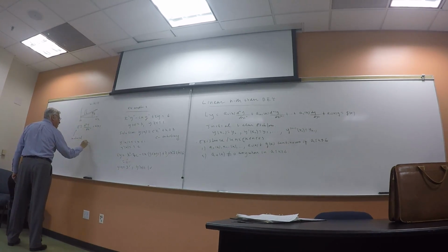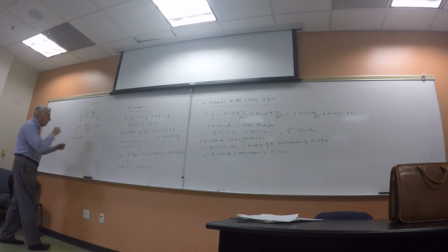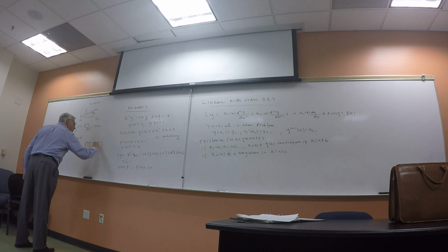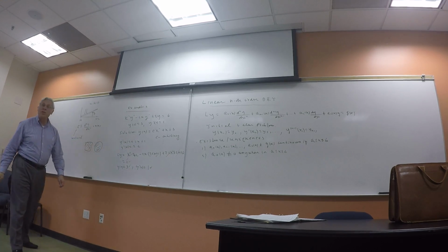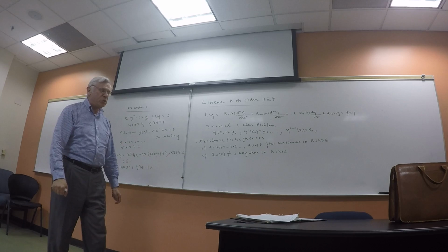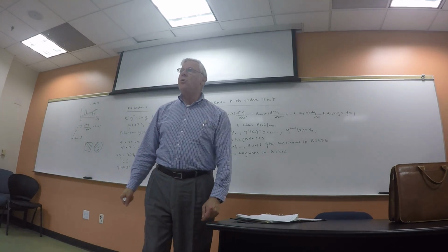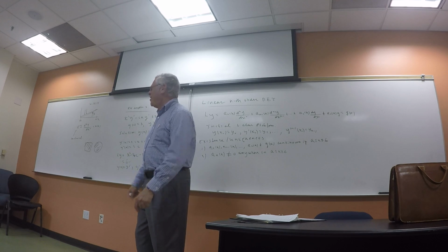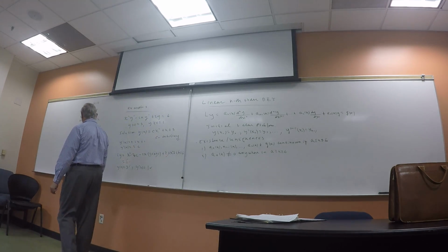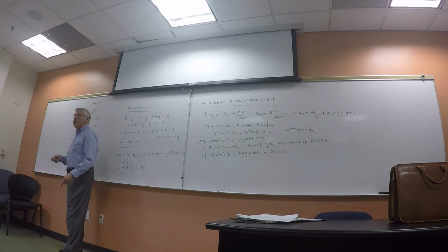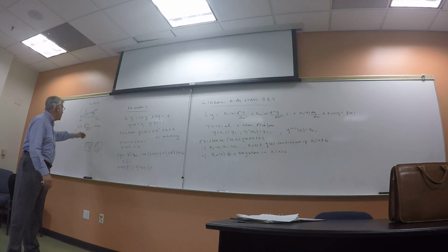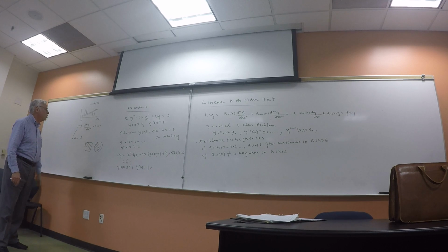So, one cross section is rectangular, okay? This is looking head on to the beam, and the other one has a circular cross section, okay? I think you could easily surmise that given the same loading, these beams will bend different amounts, right? Because the stiffness is a function not only of the material but also how the cross section is constructed, and that's why you have this EI in it. It's this product over here, which is a reflection of those two properties.